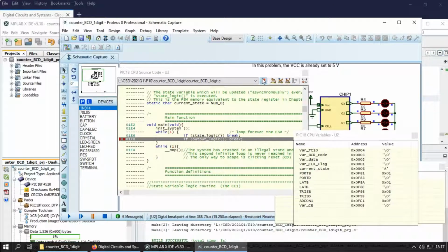but this is not that good if you think of the same circuit solved using pure hardware. Remember, 19.2 microseconds is nothing but 19,000 nanoseconds. And remember that when we did that circuit in chapter 2, we could solve it very well in 5 or 10 nanoseconds. That was the idea there.